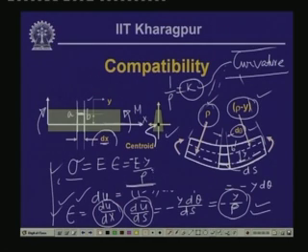Now, here you note that strain and the stress vary along the depth y, which is the depth of the beam. Now, this particular relationship which we get is basically arrived at from the geometrical compatibility of the beam, under the geometrical deformation, how it undergoes strain. So, this gives us a relationship which we call compatibility. Now, we will have to look into the equations of equilibrium, so that we can establish the relationship between the stress and the corresponding stress resultant, which is the moment.